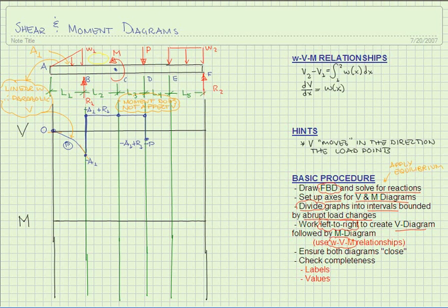Now again, in this particular region, there is no load, therefore there is no slope, and there is no change in shear between 2 points, so our shear curve continues to march along until we encounter this distributed load. Now we must find the area, and we'll call this area 2, and that's just a rectangle, or we could say that's W2 times L5, this length 5, and if we wanted to be complete over here for this area, we could say that's 1/2 of W1 times that length L1, just the area of a triangle.